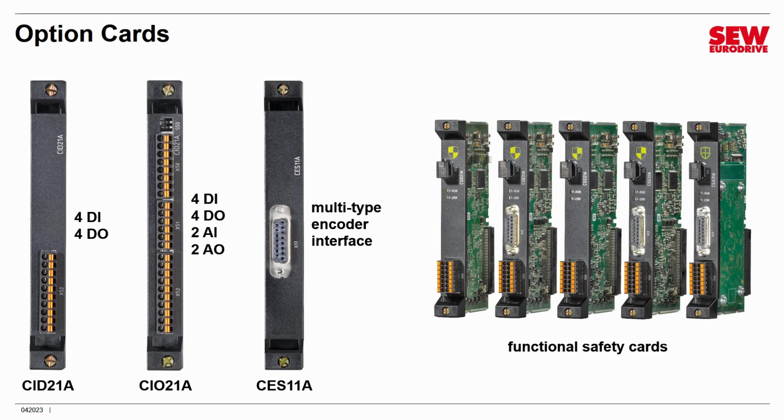They also have another nifty little feature. Once they're commissioned, they store the commissioning information in a little memory module which is swappable. That means that if a card dies, you can replace it and then swap the memory module, and the commissioning with the safety commissioning goes with it. And that means you don't have to go back through that whole process again. So that's definitely something that in the maintenance side of things is very desirable.